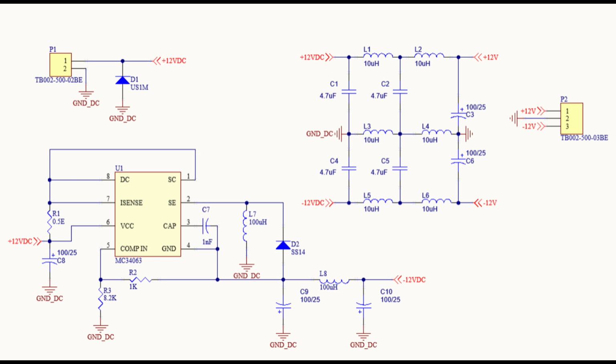The schematic has now been successfully annotated. Each component is assigned a unique reference designator, ensuring clear identification throughout the design. This automatic numbering eliminates conflicts and prepares the project for PCB layout and documentation. With this, the schematic design for our project is complete.